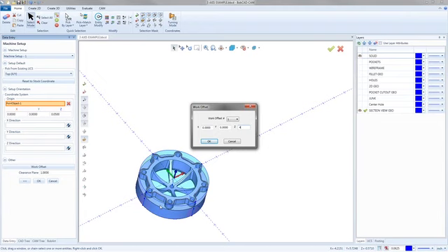If you ever launch your simulation and you hit play and you see your tools turn bright red as they're cutting, that means you're gouging something. But if your part's not turning red along with it, it usually means that you're cutting your machine. So if you have the machine view turned on, you'd be able to see that you're cutting inside the table of the machine. Changing this does nothing to the G code. It doesn't do anything to the G code. All this does is shift the part up inside the simulation.